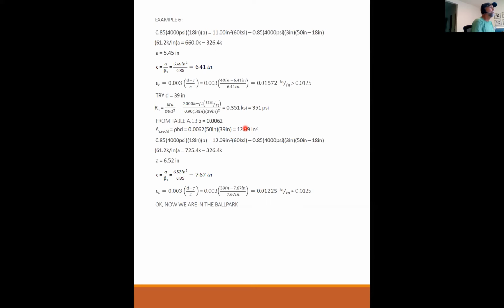So when you draw your moment diagrams, if you draw your moment diagram correctly, you will see that some of the beam is under positive bending and the rest of the beam is in negative bending. And you need to pick where is the largest magnitude of positive bending and where is the largest magnitude of negative bending.